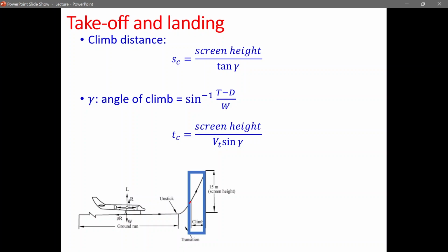So when the airplane is 50 meters above, it's considered takeoff? Yeah. So you have already taken off. Yes. Is that height going to be the same for all classes of aircraft? Yes. That is essentially based on that 15-meter height, which tells you that you have surpassed the average height of the buildings and trees and everything, right? So you are already in air. That is not necessarily true for everything, but there's an average. It's just a convention, right? So it doesn't really matter what aircraft you're flying.